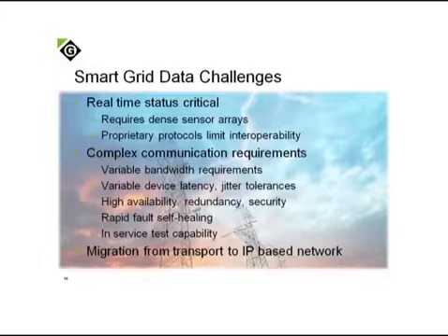Part of the complex communication requirements also is that each one of these sensors has various bandwidth requirements. Everything from, say, 16 kilobits every 5 minutes for AMI, all the way up to maybe 1.5 megabits per second for a synchrophasor that's in active mode that's continuously sending information across the network. Obviously, that type of operational data has very high priority standards, very low latency, and very high uptime requirements. Whereas some of the non-operational traffic, best effort Ethernet, intranet type access, higher latency, less availability is absolutely acceptable.